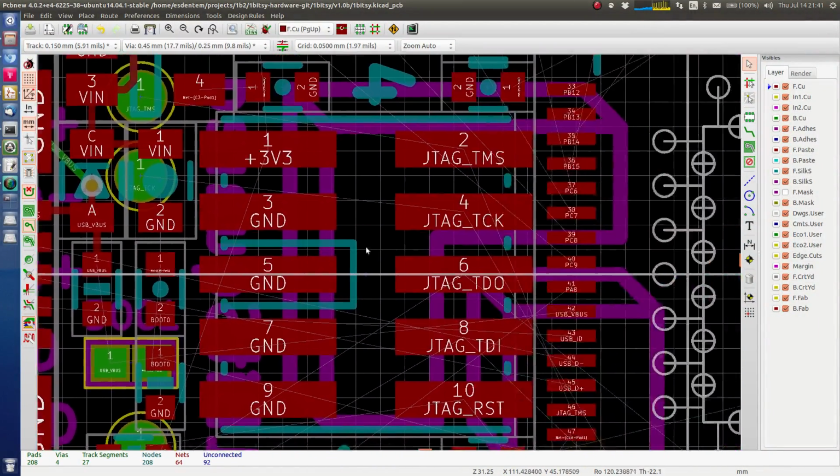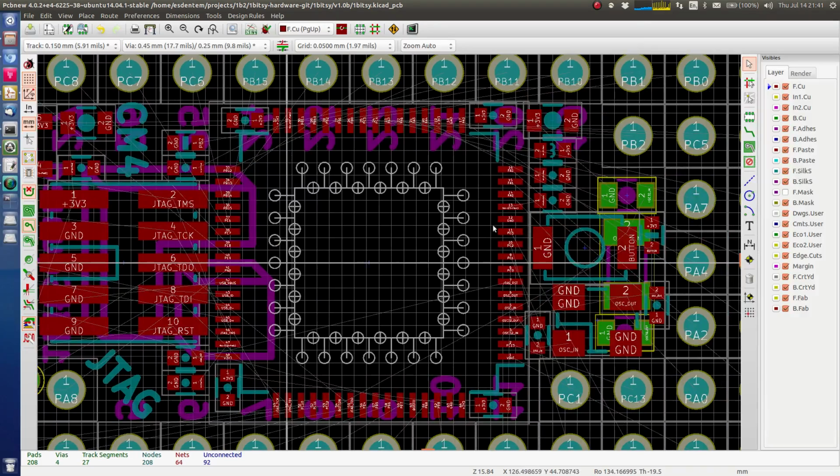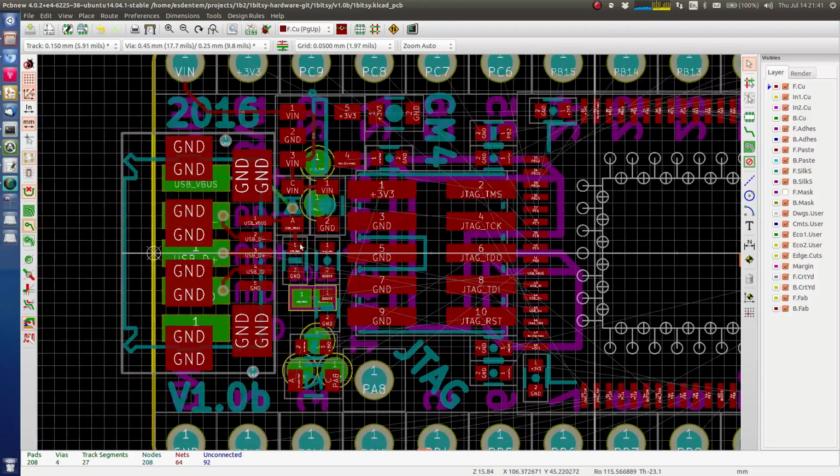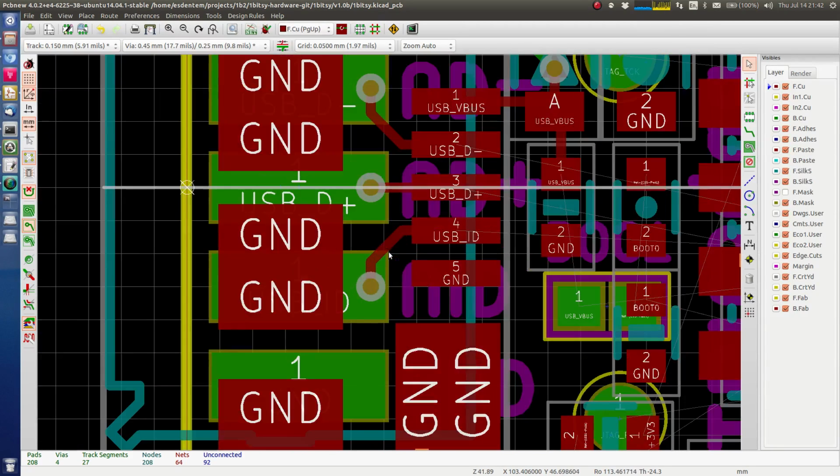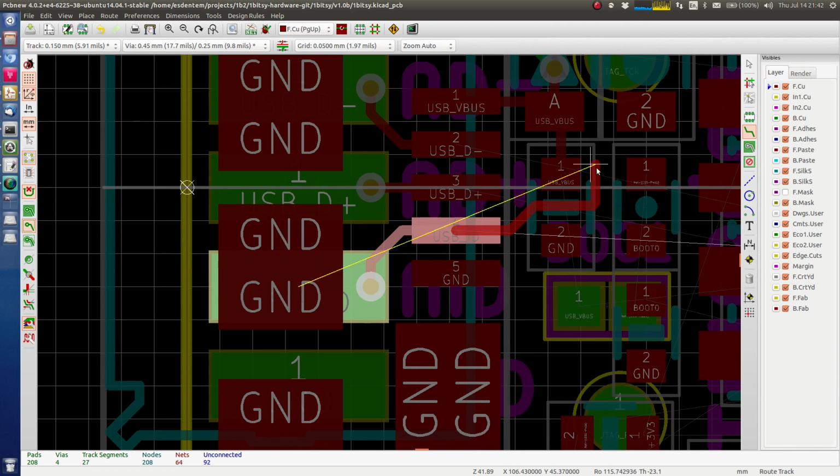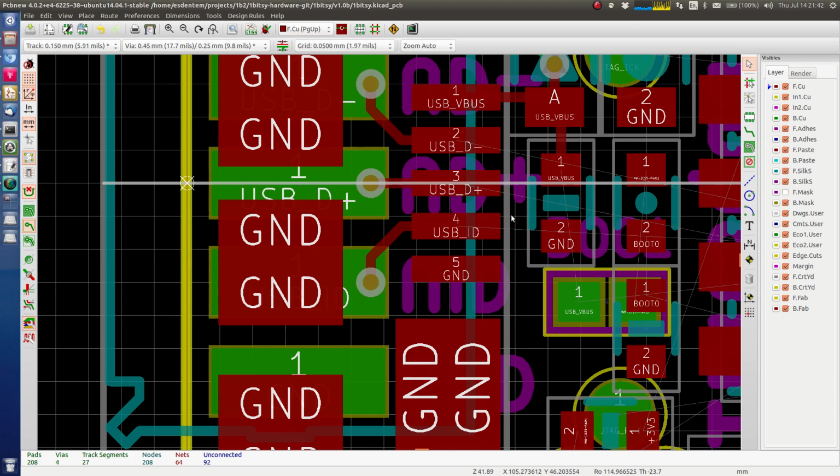I understand if you have a monster like this that it might not be possible, but if you have a resistor or a capacitor or even a USB connector, this should still keep these traces aligned. If I do a trace, it's nicely attached and it's doing all this nice squiggly stuff, but it's not doing it if I drag a component.